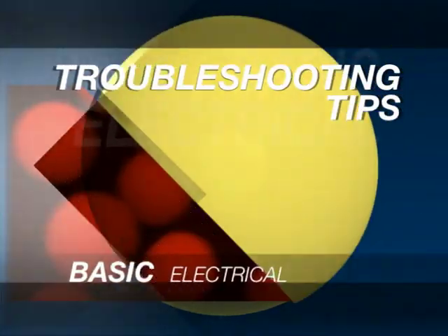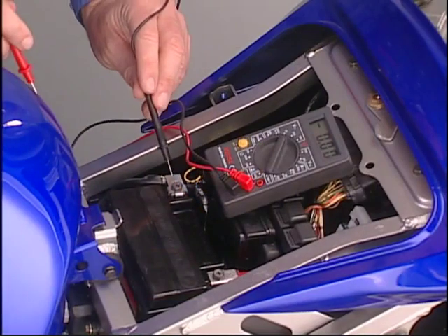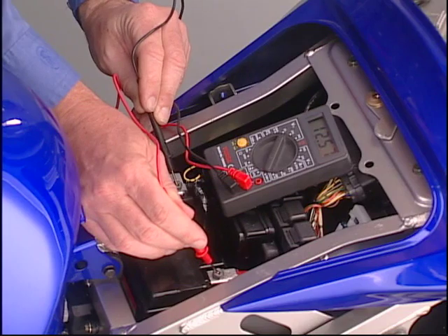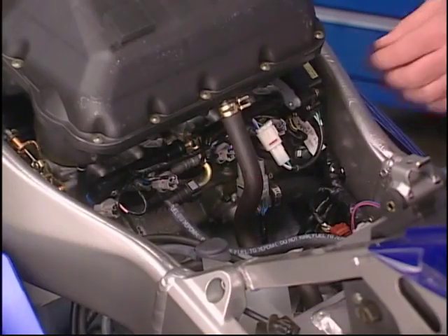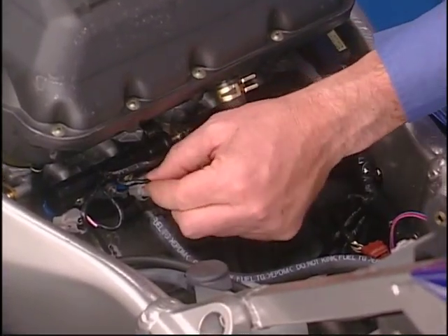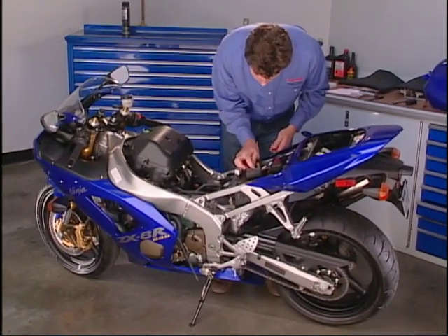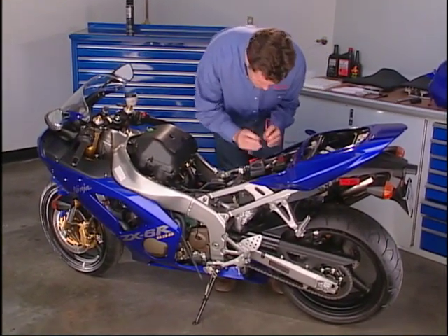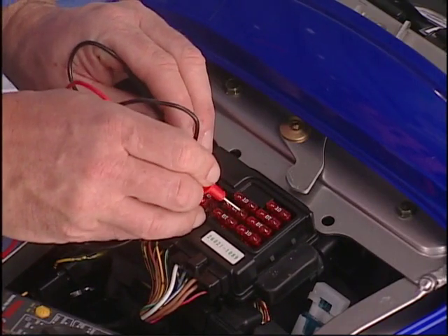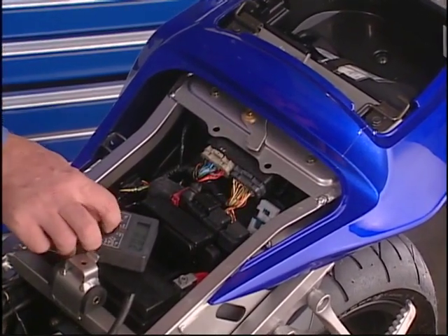Following a few simple tips can make troubleshooting an electrical system a whole lot easier. Always check to make sure the battery is fully charged before beginning any work. Make sure all connectors are clean and tight. Start the diagnostics process by checking the simple things, such as a continuity test on the fuses. Many tests can be done without taking apart the whole vehicle.